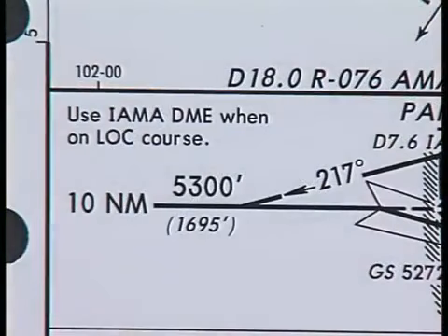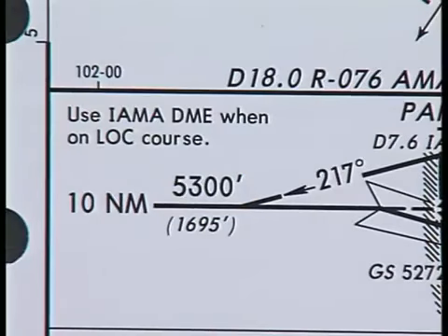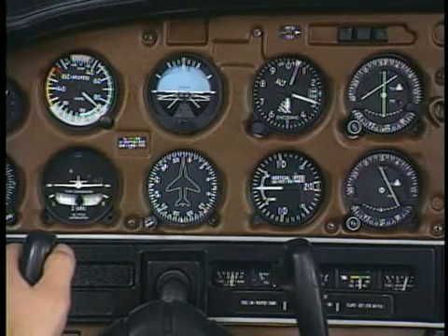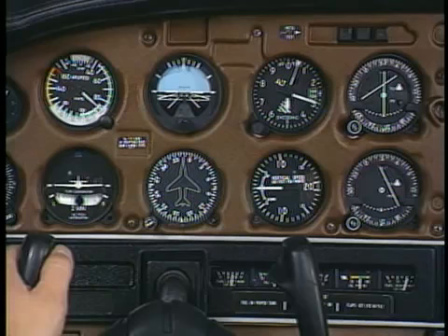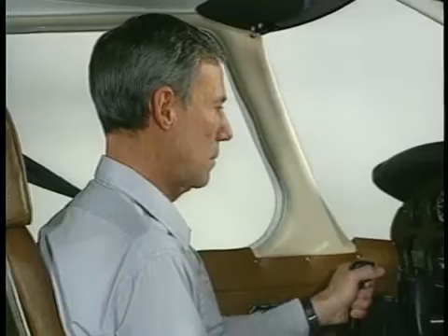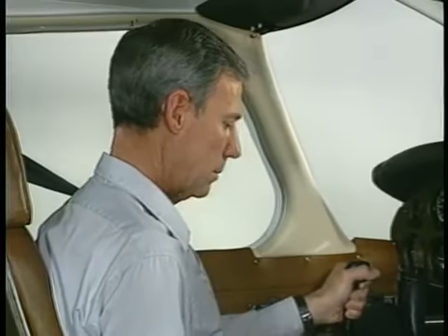Your minimum altitude from the procedure turn inbound is still 5,300 feet until you intercept the glide slope just before you reach Pandy. Your primary concern at this time is to stabilize your airspeed and altitude, and find the heading that maintains the localizer centerline. Intercepting the glide slope at the proper speed makes the descent more stable. This is also a good time to verify the decision altitude and height for the approach and the missed approach procedure.